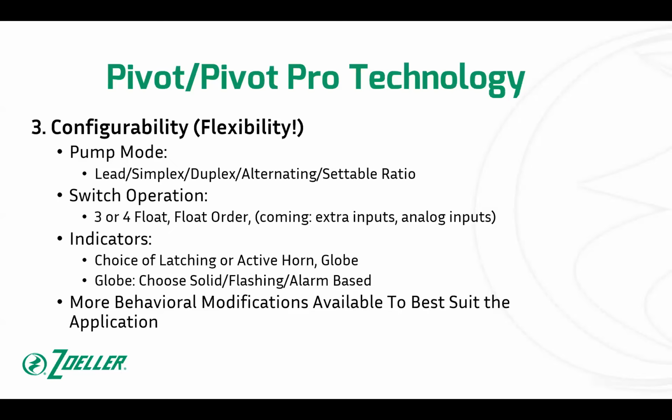You can have it be 73-to-27. Whatever the ratio is you want. There's 2 digits on each side of the colon. And what that does is it allows you to put most of the wear on one pump, or almost all of the wear on one pump, and maybe just have an exercise cycle for that second pump. So hopefully that wasn't too confusing.